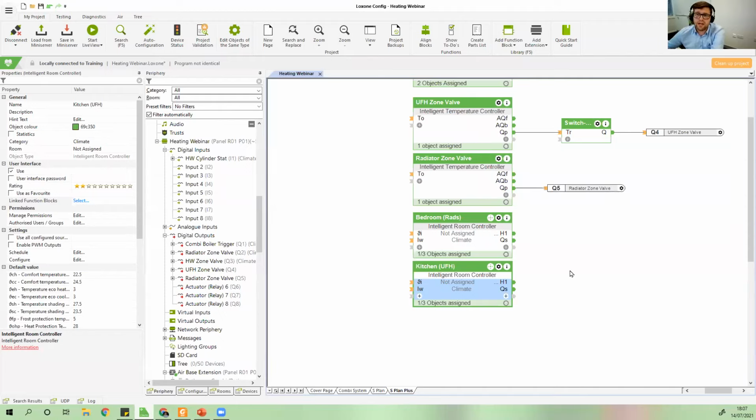I mean, you could equally argue that if you're putting live through a cylinder stat, which is then feeding a zone valve, the relay in that could become fused and it could hold the water on forever as well. So you've always got a potential point of failure. You've always got something that could fail. And what do you trust? I trust Loxone. It's down to you as a professional decision whether you do as well.